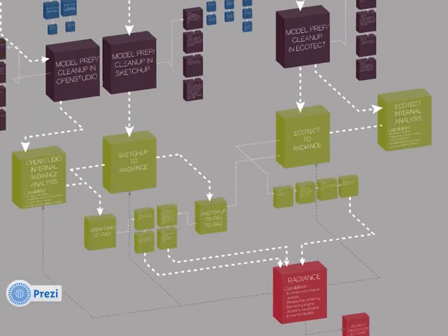So, almost to the bottom of the diagram, this is about the different analysis options you have after you clean up that model, depending upon what stream you took. It's worth mentioning that there are two internal analysis pathways, OpenStudio and EcoTect, where you can stop there. Once you get the model in and clean it up, you can perform analysis directly within those programs. The other two pathways focus on getting it to Radiance in a flexible format so we can do all of the high-powered analysis that we can do in Radiance. At the lab, we have generally tried to get it to Radiance, but in practice, you might be able to stop here depending upon the nature of the analysis you are looking for.